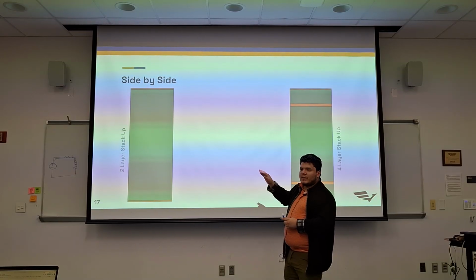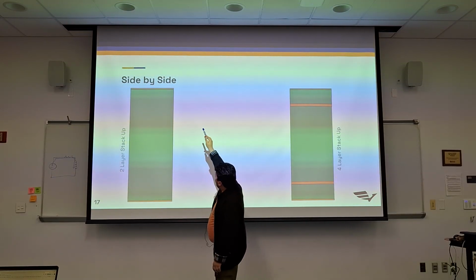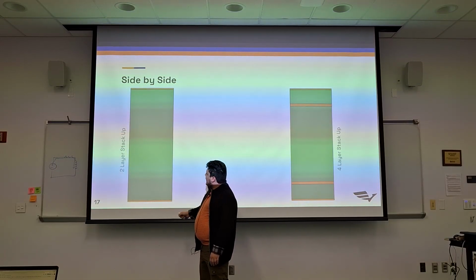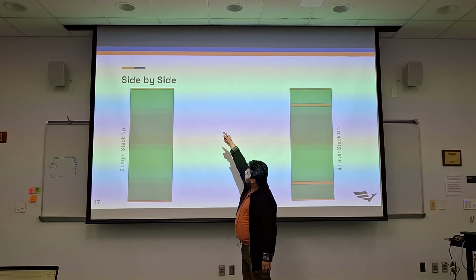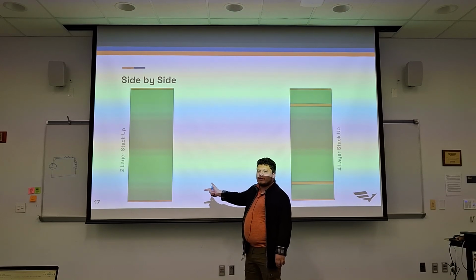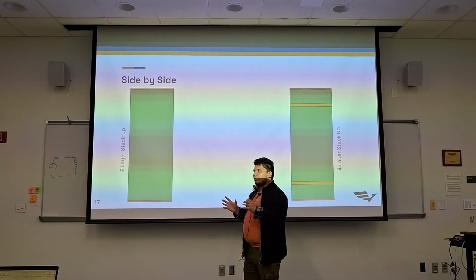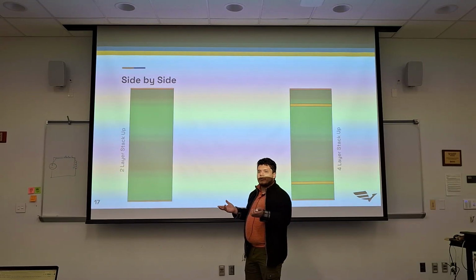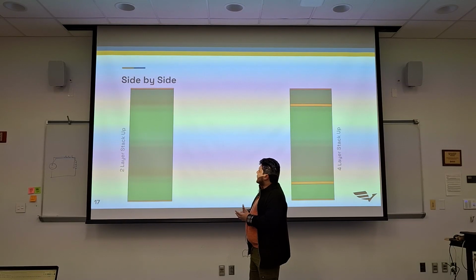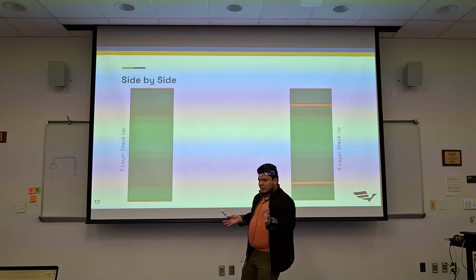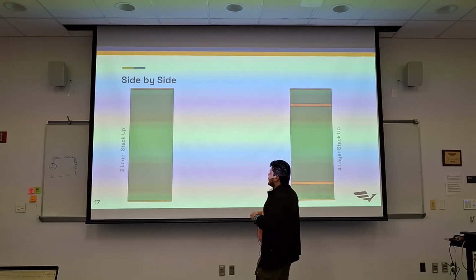Obviously when you have a via, so if we have a via at the very top trying to get to the bottom, obviously the signal has to cross through. And so if you're going from there to there, your signal is traveling 62 mils down the via. And there's no guarantee that that via is shielded because it's just going across a bunch of FR4 material that can also have signals around it. So you generally want to avoid via transitions as much as possible. That's a nice golden rule.